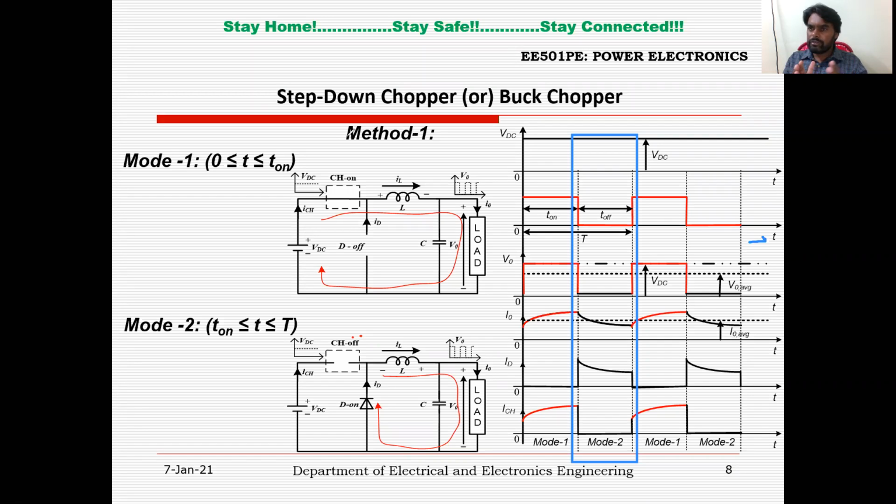We are not bothering about the circuit configuration for the commutation circuit. So here the role of the commutation is to make the chopper off. So now if the chopper is in off condition, you can see like this, it is replaced by open circuit. Right? Now previously the inductor was charged to some extent. Now the inductor has to discharge.